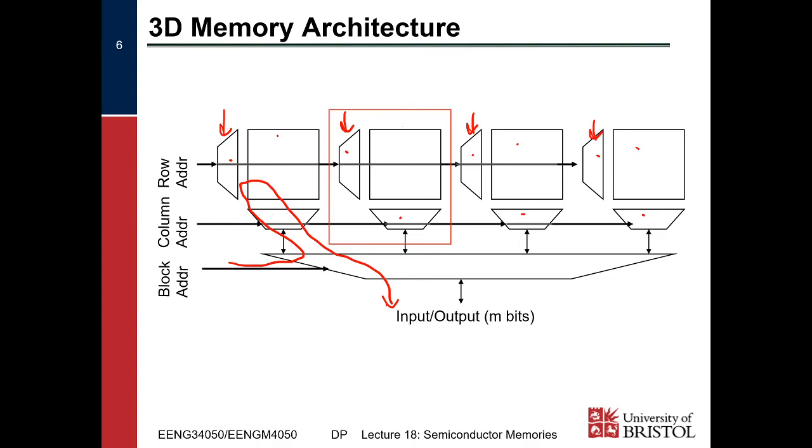So this is quite a problem. As we increase the number of dimensions, because we've got more layers of logic between the actual memory cell and our data and our address lines, the memory gets slower. So we need to consider what the appropriate number of dimensions for our memory is, and this goes back to our caches. We can have lower dimensional memory close to the processor with smaller amounts of it, and hence it's going to be faster, and then we can have memory with higher dimensions further away from the processor, where we can accept the delay.